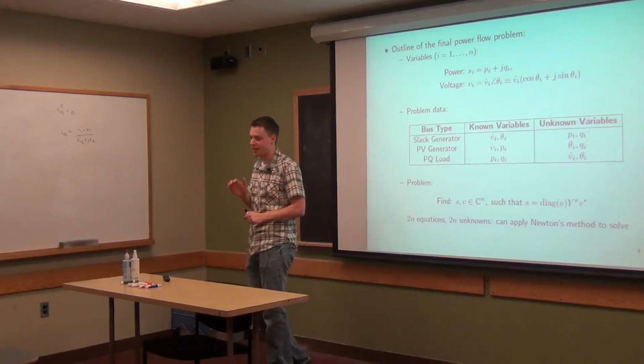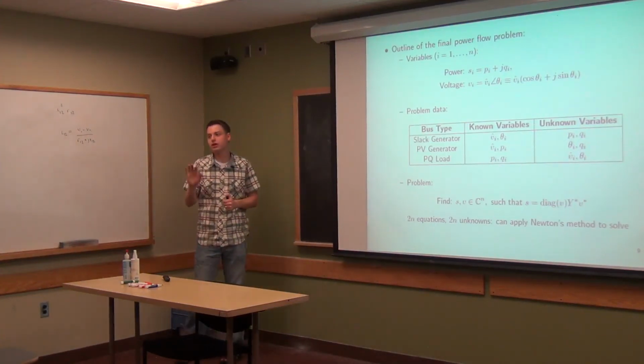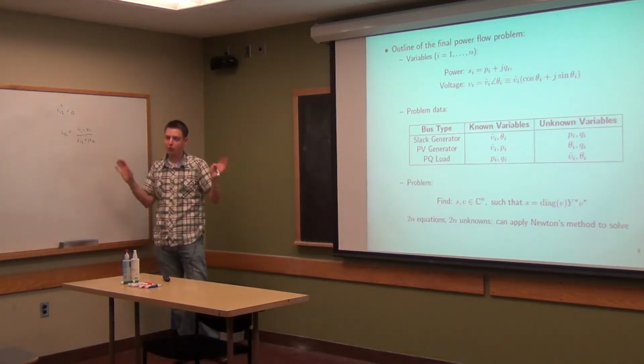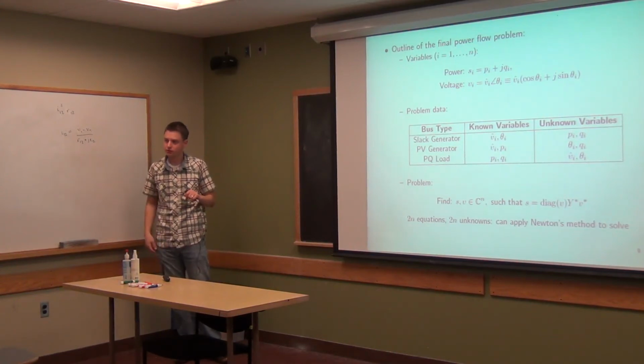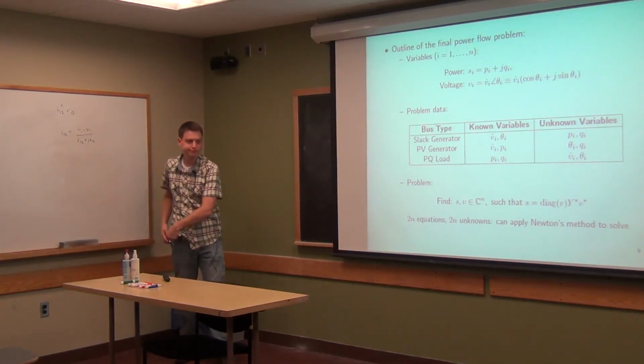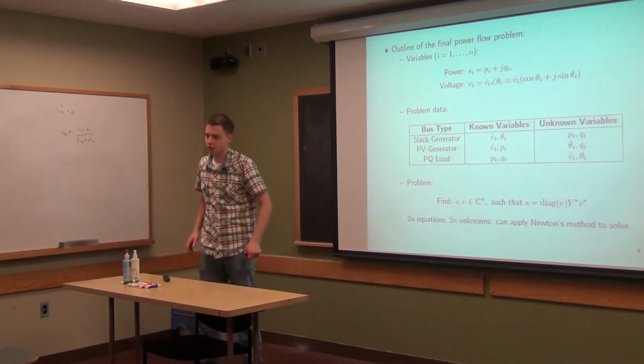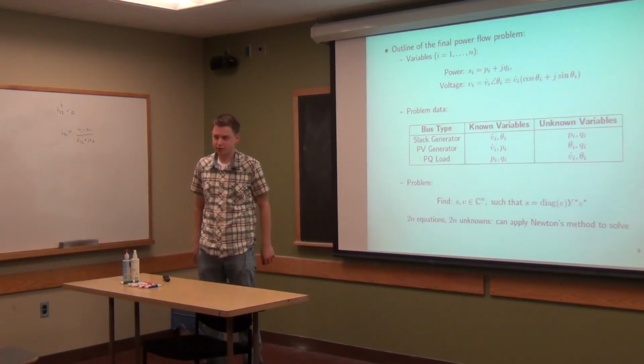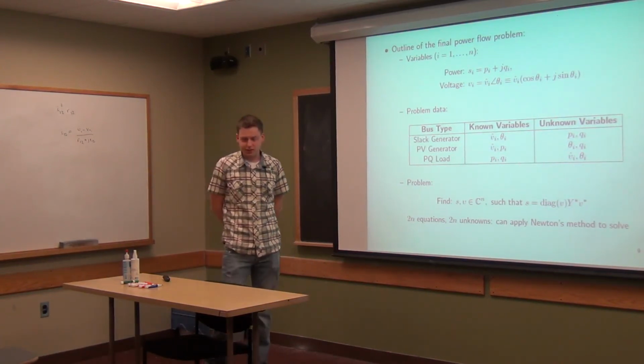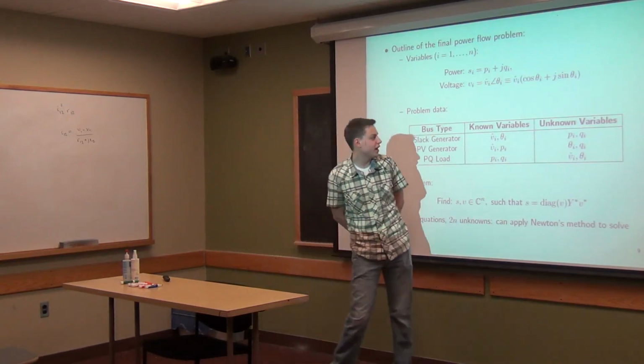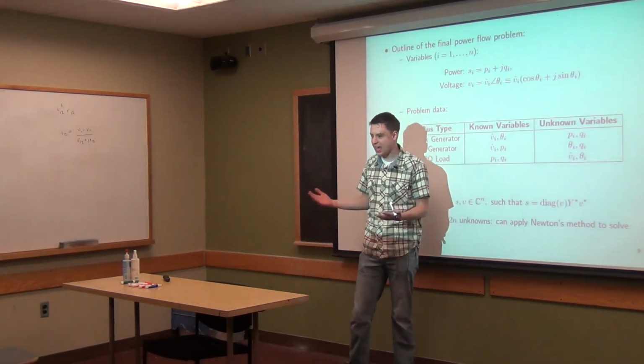So what has to happen in some sense is that we have to take one node and say, well, we don't really know what the power is there, at a generator, that is. For the rest of them you know the power, and only one of them you don't know. Yeah, exactly. If there were no losses in the network, then we could know all the powers, right?